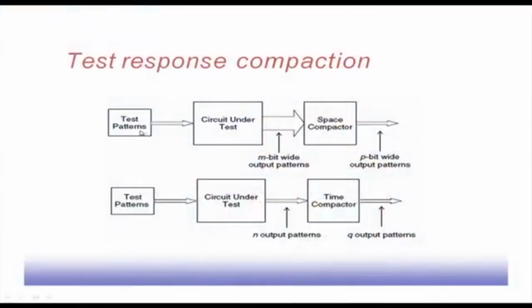Test response compaction. The overall diagram can be shown like this: the test patterns are coming from the ATE. There may be a decompressor here, which is not shown explicitly. After decompressing, the test patterns are applied to the circuit under test.